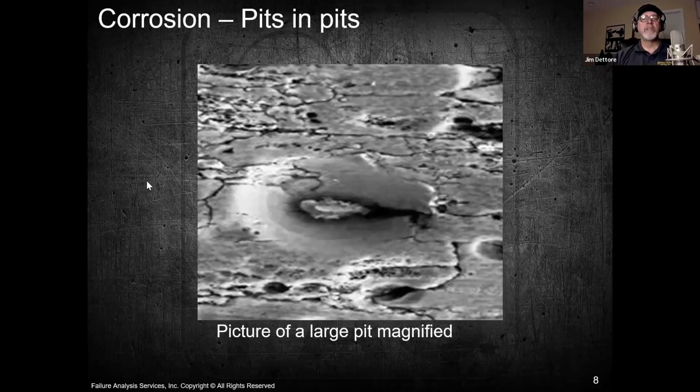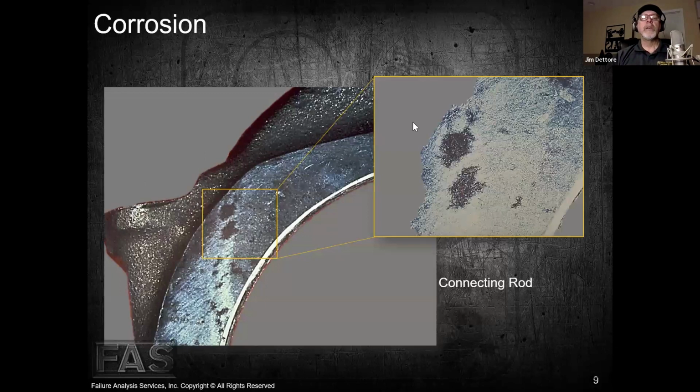So, all right. Again, on the internal component parts, and when we talk about corrosion and the pits that it leaves behind, this is the side of a connecting rod. This should be a very smooth finished machine surface that should have a specific surface roughness. So if it bumps into another rod that's right next to it, it's not going to cause any damage or any accelerated wear between the surfaces. So when we see these pits, well, this rod is made of steel. So as this pitted, it released secondary debris, again, in the form of iron oxides.